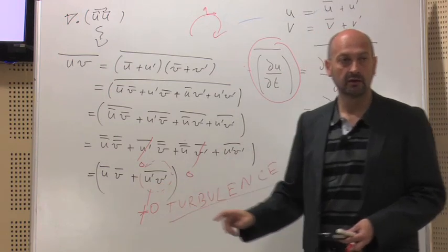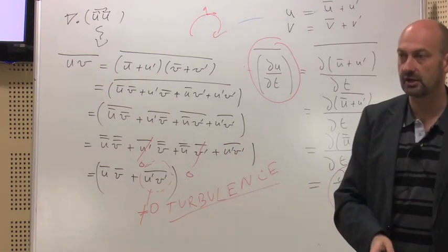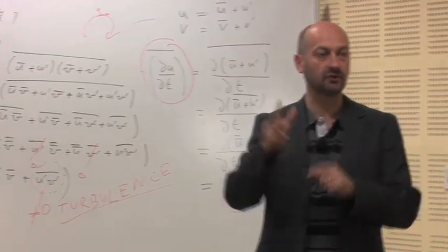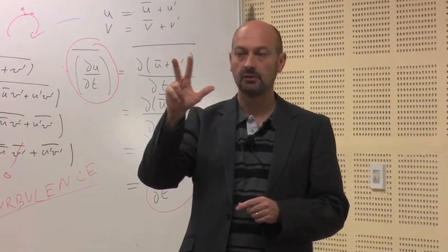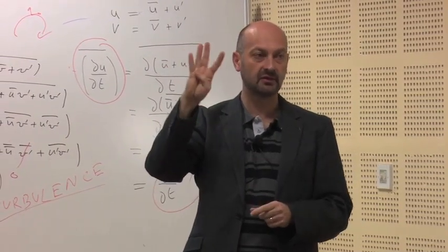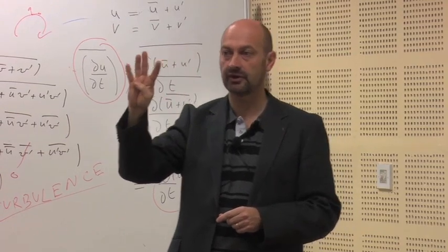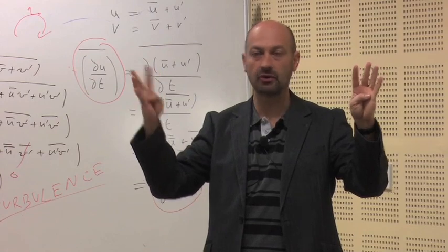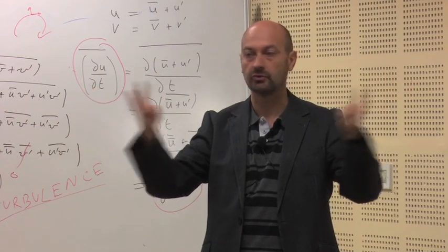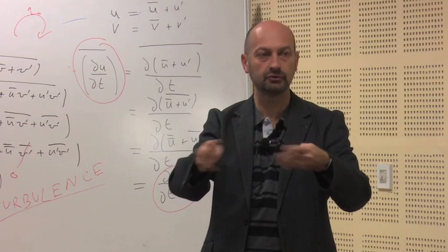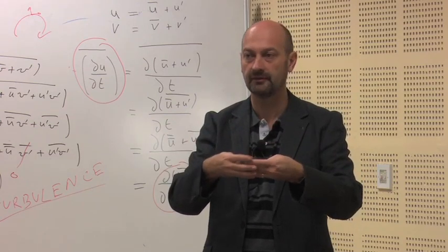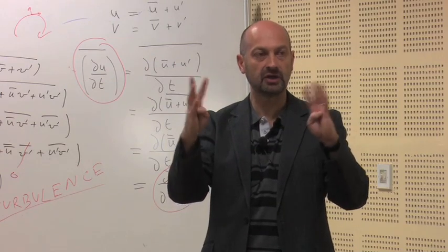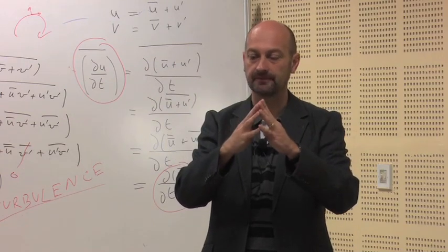Okay, so initially you start with equations which are closed. I mean, in the Navier-Stokes equation, you have 3 equations for the 3 components of the momentum balance, plus the divergence of u, so that is 4 equations. Okay, you have 4 equations. And you have u, v, w, p as unknowns. So you have 4 equations, 4 unknowns, so that should match. Maybe you don't know how to solve it, but there is a solution, and the flow is actually the solution. You can see the flow, but this is the solution. So you can match the two, and indeed you can find the solution.